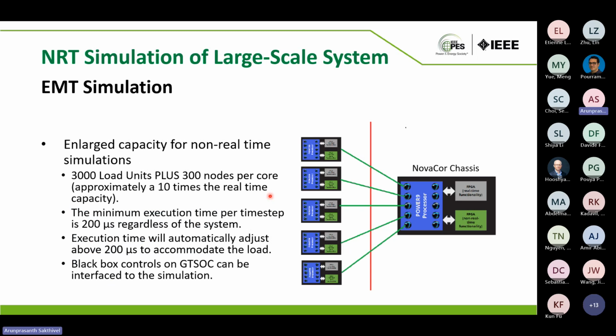Okay, so talking about non-real-time simulation option for large-scale systems. RTDS has lately worked on a non-real-time simulation mode to enlarge the capacity of the simulation. Basically, whatever you could put on one chassis could be simply put on one core of the NovaCor chassis to enlarge the capability. So it gives approximately 10 times larger network that we can model on one chassis to be modeled in non-real-time simulation mode.